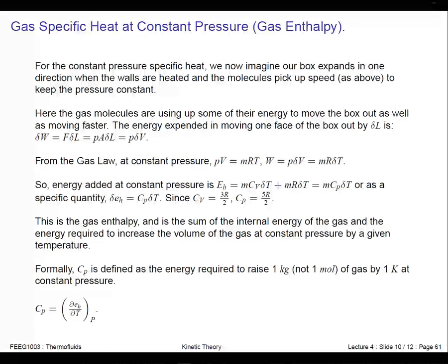When you heat this gas, the temperature is going to go up and the pressure will go up, and because the pressure goes up, the piston will rise because the force pushing up is bigger than the weight pushing down. Then the volume of the gas expands, and the pressure reduces, and eventually you get to a new equilibrium point where the force acting up through the pressure in the gas is equal to the weight acting down.